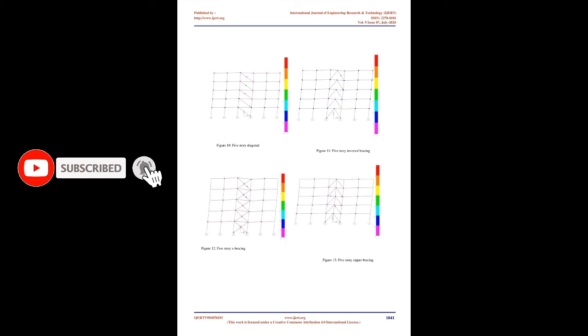In this study, each CSB steel bracing made different displacement, and their strength was different from each other, but the unbraced frame joints are not stiff enough, and failure happens, so the unbraced frame becomes the weakest frame compared to the other frames. The result is shown in a capacity curve, figure 7, so the curve clearly defines that inserting steel bracing in the existing structure dramatically increases the strength of the building and allows the building to stand high lateral loads.